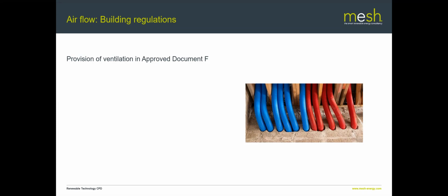So that's bathrooms, kitchens, utility rooms, and also places like gyms, certain storerooms, boot rooms, those kind of things, where you might be putting wet clothing, you might be having showers or baths, where you're producing steam, or cooking, where you're producing steam from cooking. That's where you'd extract from, and then you're basically supplying air to every other part of the building.